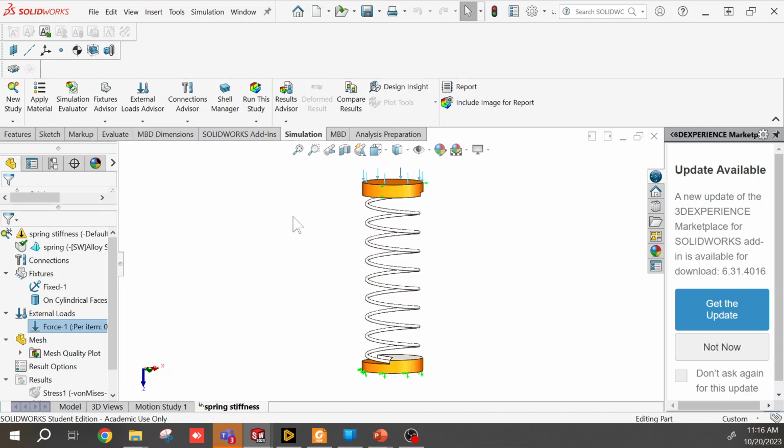It will compress. What if you didn't have your thumb perfectly aligned? What would happen? It would fly away off the side of the table. Okay, so that's the most critical mistake or oversight that a lot of students make: if you don't tell the solver to suppress or stop something from happening, it's a valid physical outcome from the simulation.